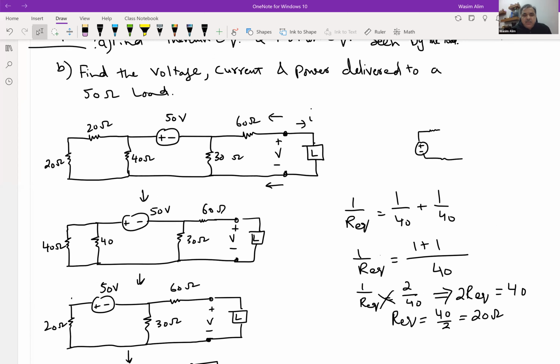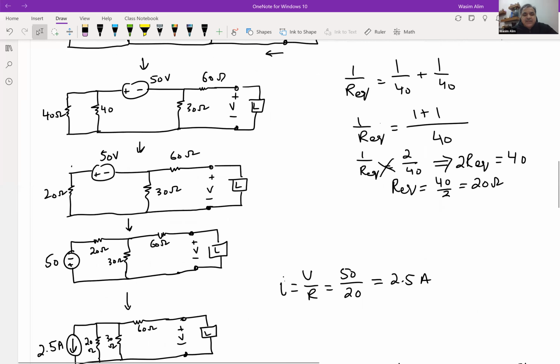it will be a little bit more work, because you will have to bring the circuit to at least this form, and then be able to apply the I short circuit and V open circuit. And you could use the node voltage technique, or the mesh current technique, to find these quantities.